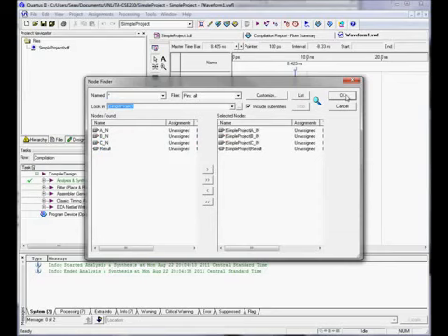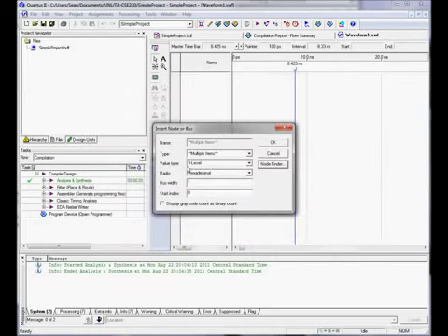There we go, we want everything. It's going to say multiple items. We have a different radix that we can sort here. So if you have what's called a multi-vector bus, in other words, if you have multiple bits on the same line, it'll give you the option of seeing it in ASCII, in binary, in hexadecimal, octal, signed, unsigned, all that fun stuff. We really don't need to worry about what we're doing here, so we'll just leave it in hex.